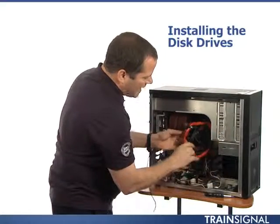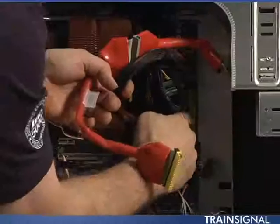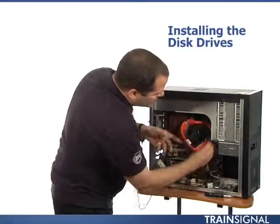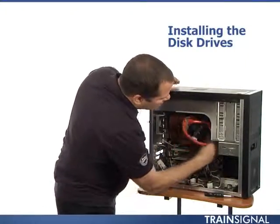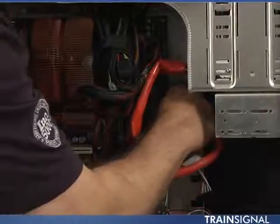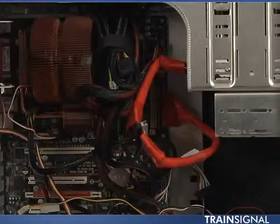Now here is the back of the connector. And it goes in this somewhat secluded spot on the motherboard here, which is an ATA type of connector. And you simply line up with the notch that's here, and it slides and pops right into the motherboard like that.